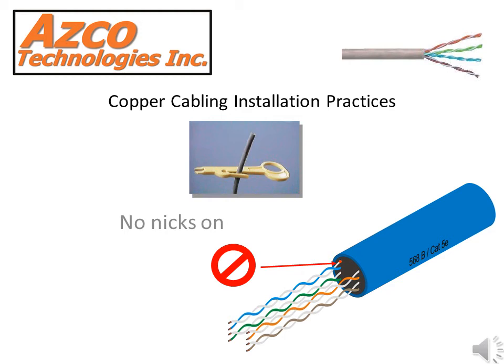At termination, the installer must be cautious in using snips, cutters, pocket knives, or stripping tools when removing the cable jacket, so as to not cut the insulation of the actual pairs on the inner conductors.